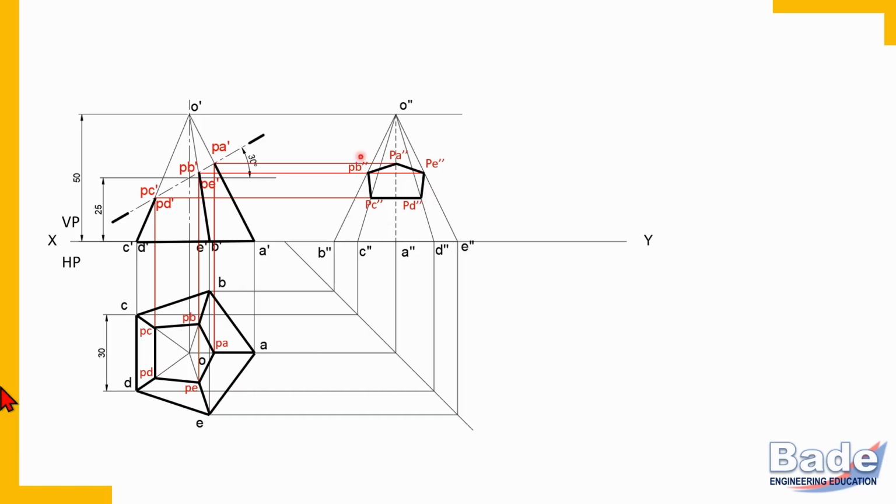Now the retained portion in the sectional side view. Again, all base edges are retained. So I made all base edges dark, and face edges below the section, that is PE to E, PD to D, are dark. Now sectional views are special purpose views. Hidden details are not necessary in sectional views. And one more thing, inside the section, there should not be any edge, any single edge. A hidden edge or visible edge will not appear inside the section.